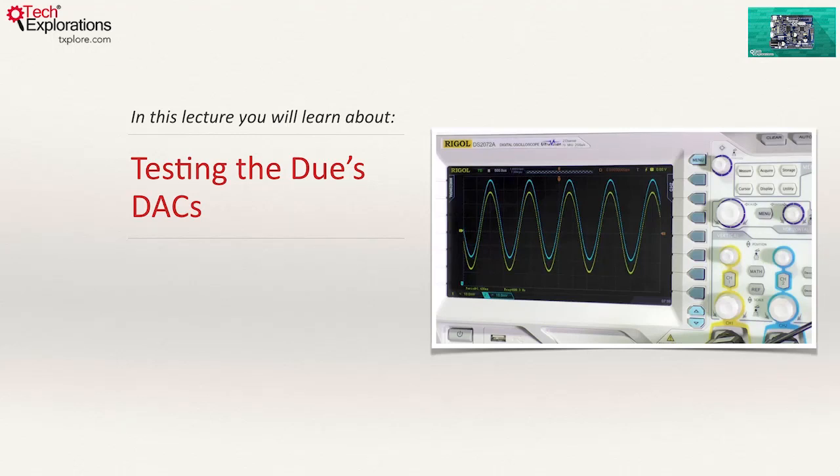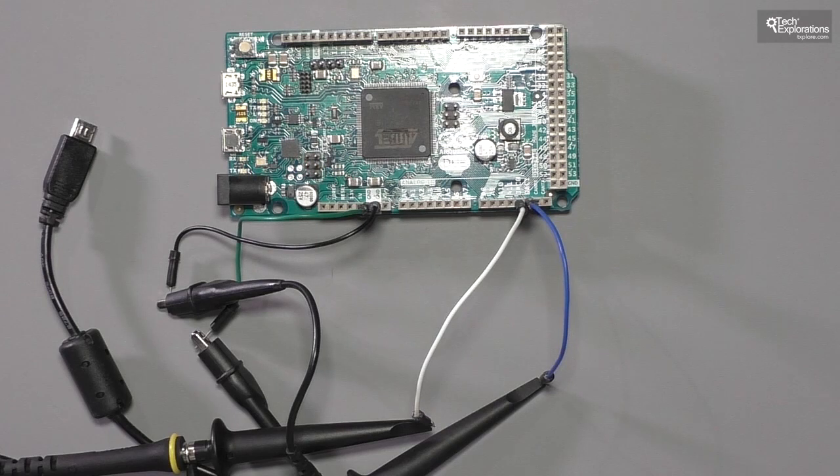I will use a demo sketch that creates a sine waveform and compare the output at two resolutions, 10-bit and 12-bit. Will you be able to notice a difference? Let's see. In this lecture, I'd like to play around with the Arduino Due's true digital to analog converters.